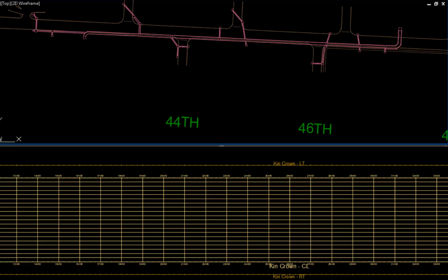The drawing shows two viewports with plan on top and profile on bottom. All layers have been turned off except C-Storm, Road Concrete Curb Improvement, Existing Road Names, and C3D Profile View to allow easy selection of the C-Storm parts. The road alignment stationing and road profile views are generally used for the storm objects that are installed within or in close proximity to the road.